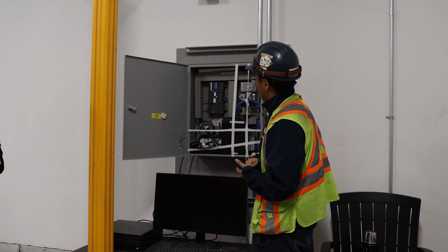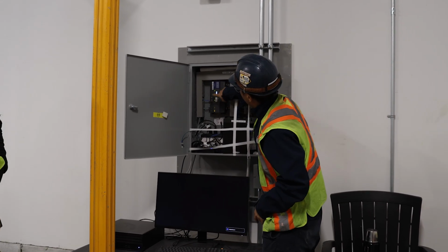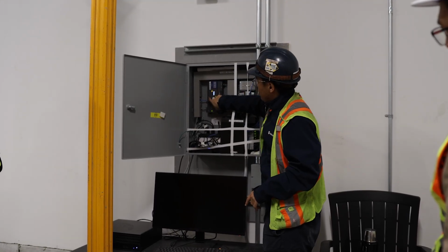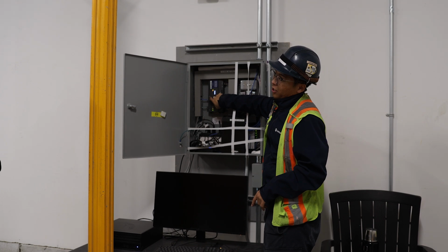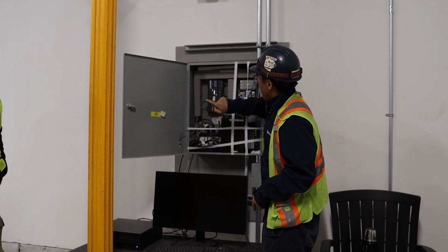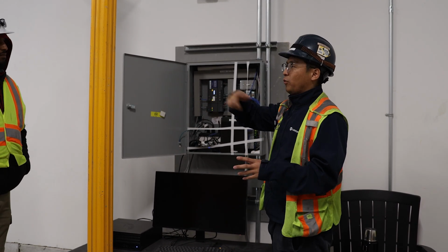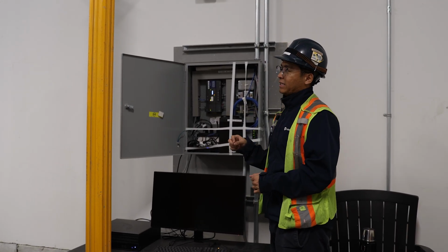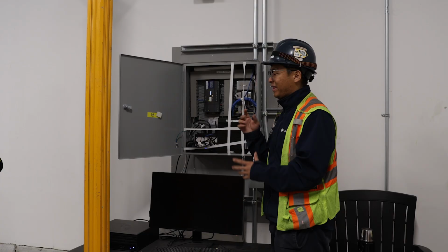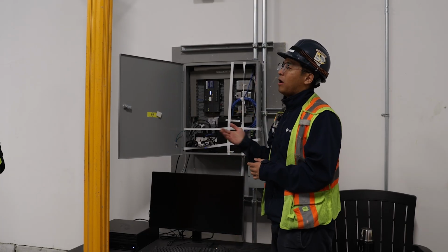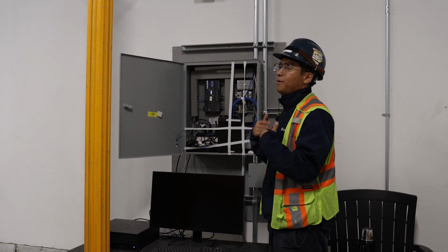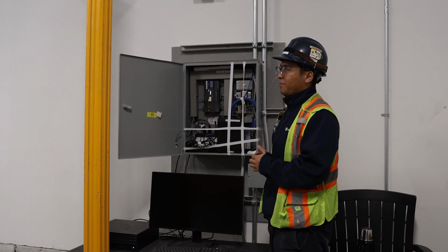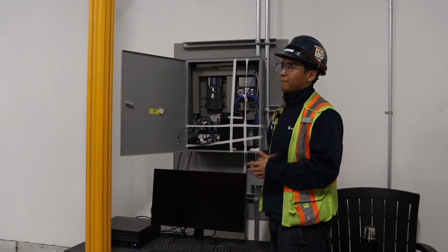We will have to work with IT to set up the building network and pull another Cat5 to the secondary port, so the controller communicates with the building network and also gets internet access. With internet access, we can set up the email alarm, so an email will be sent to you through text message or to your email address if there's an alarm.